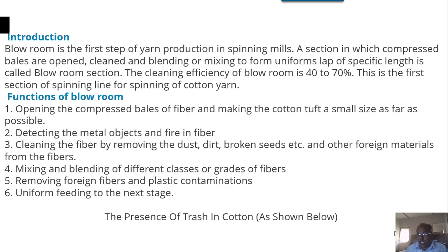So, as per the count that is going to be spun in the department, as per the production planning, we are required to have evolution of the mix. Evolution of the mix in the sense a particular count, say for example, we are spinning tens carded. For that, how many number of cottons should be there? What should be their proportion of mixing?